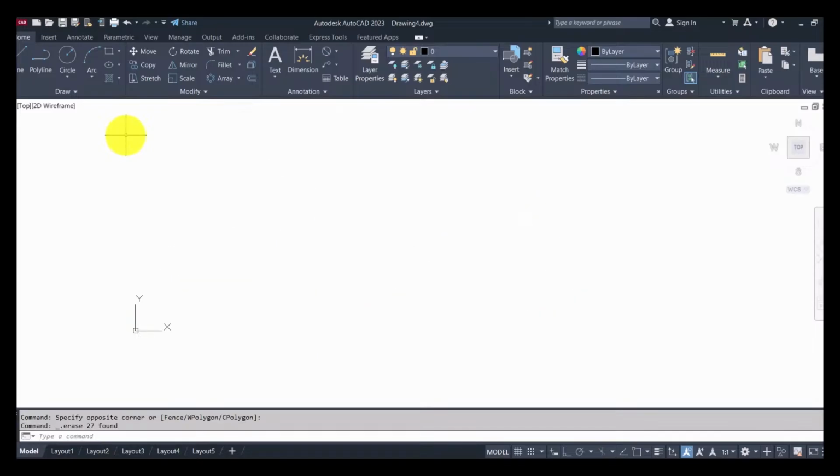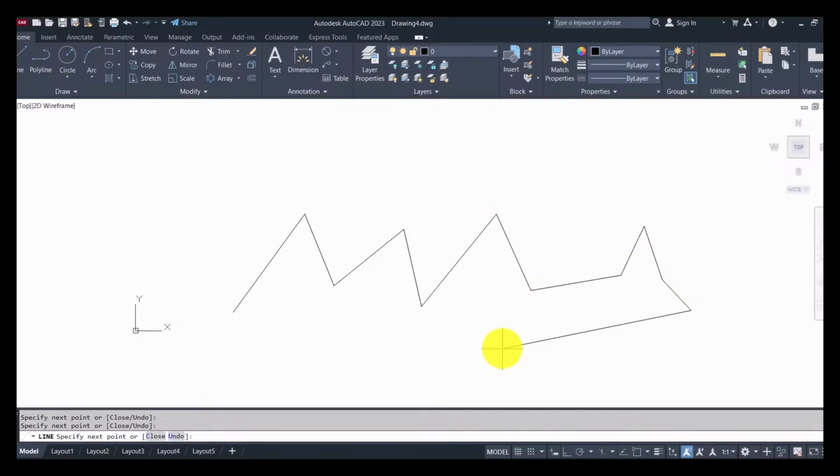Generally, we always have one default option on our command line, but we can have as many alternative options. You can always click on the particular option from your alternatives to decide on what you want to pick. Depending on the version of AutoCAD that you are using, in some older versions you will not be able to click.